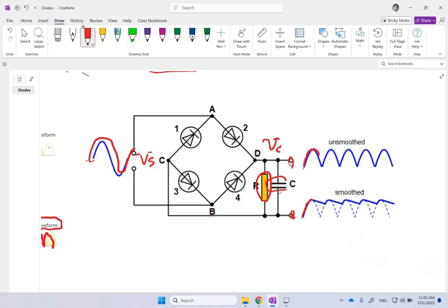Your Vc is fully charged, so let's say 5 volts, for instance, or 10 volts or whatever. So this is 5, your Vc is now at 5. Your Vs came from 0 to 5, it charged it. Now when Vs goes down, so let's say it goes below 5 volts, and your Vc is 5 volts, Vc is starting to discharge, right? Because now your Vc is bigger than Vs, so the charge starts to go back and starts discharging, okay?